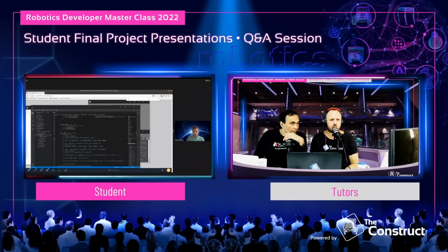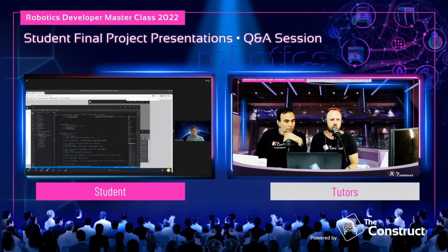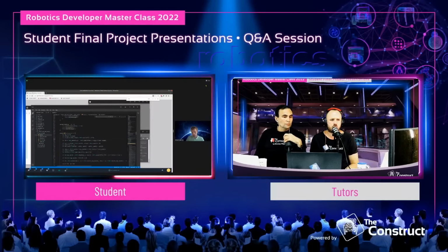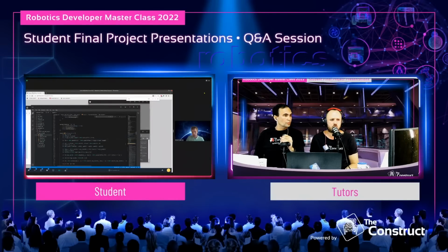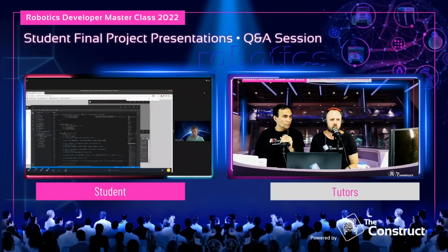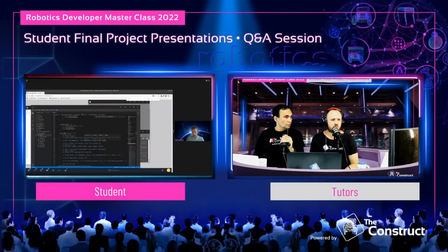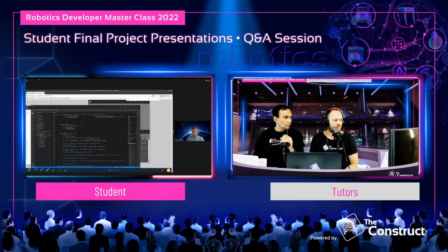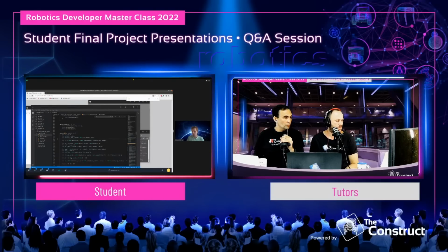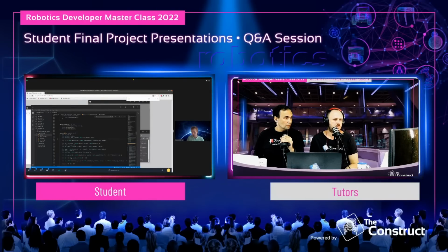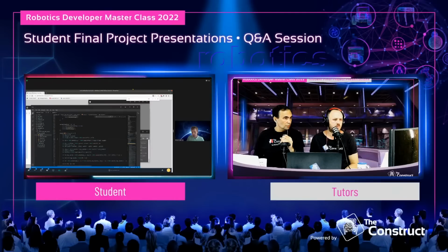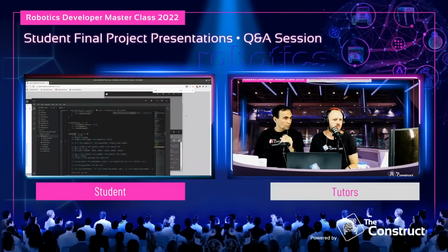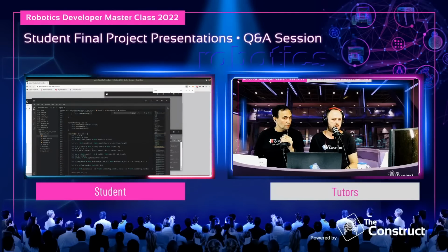So you can solve for the first angle. It's really just a function of how far out the point is. You solve for the adduction abduction first, and then once you solve for that, you know how far out the point is, and that gives you the angle between the second and third links.